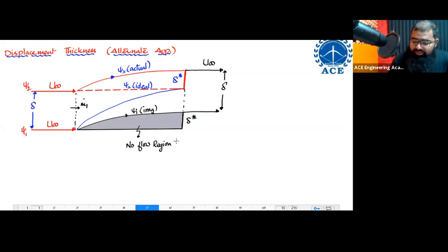Actually, over here flow is taking place. This is the imaginary part. So I'm imagining how much flow region should it sacrifice so that later on it is having a uniform velocity profile. The distance perpendicular to the plate is known as your displacement thickness. This is one more idea, very, very important idea for displacement thickness. I hope you are following this thing.